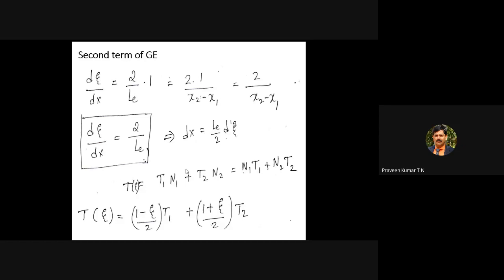We have kT equal to Q, which is the global thermal equilibrium equation. By using kT equal to Q, we have already solved one problem, getting the temperatures T1, T2, T3, etc. Those temperatures are only at the nodal points.